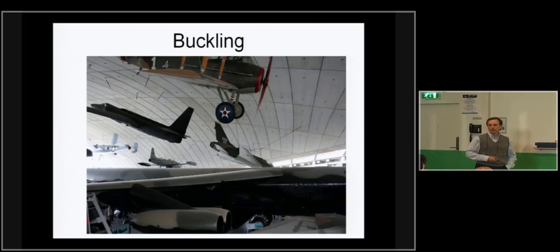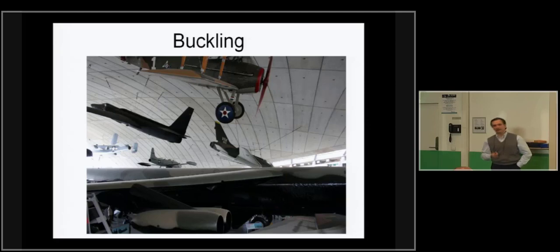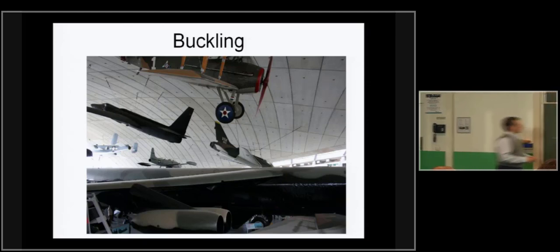And that's the end of solutions, stress solutions that we can get accurately, exactly, in fact, by solving the governing equations or minimizing the energy. We will now move to a completely different type of failure, which is buckling, and we will start with buckling of plates. The reason for that, instead of starting with buckling of beams, which we will do later, is because some of the buckling of beams cases can be seen easily as special cases of plates, and it's easier to do it that way. This, unfortunately, is not a very good picture because of the lighting on my screen.